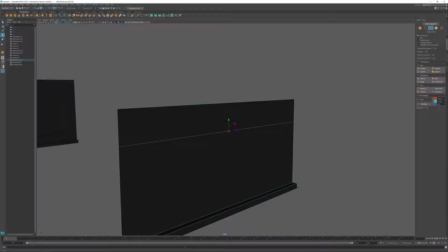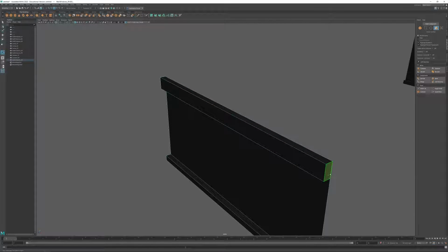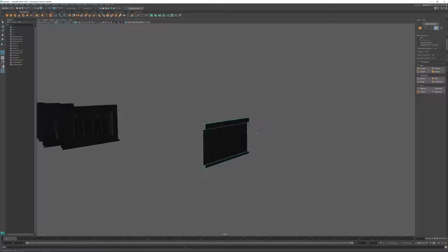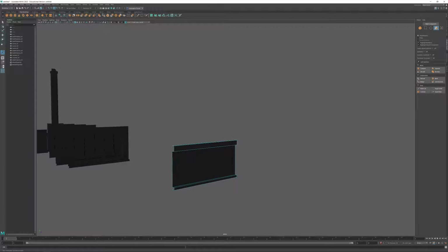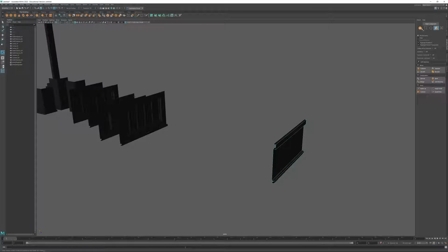I don't think that's small enough. Let's go a little smaller, 175. There we go. And again, I'll use a little bit of an extrusion. I like that thickness of 12. Keeps things a little consistent. And we can go and delete these side faces. And there, we now have the piece that's going to be along the top. And again, I can clone this to make the one that's going to be, let's get rid of that snap.